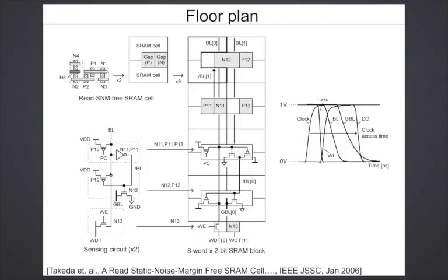But when you have such a large number of devices, essentially it's an OR functionality, right? It's like a MUX functionality. So you can't have a full static CMOS implementation of this MUX because you just blow up the area. So you have to do it like this. You have to have some weak pull-up. But this is an important failure point, I think, where you have to pay attention and see how to make it work.